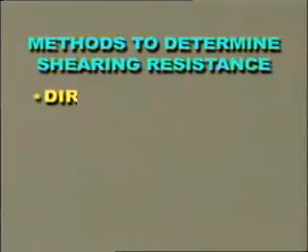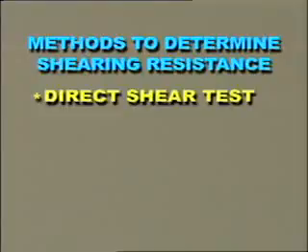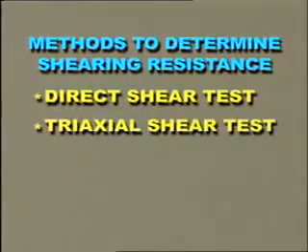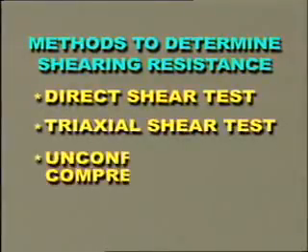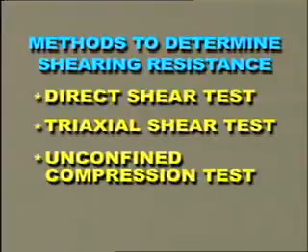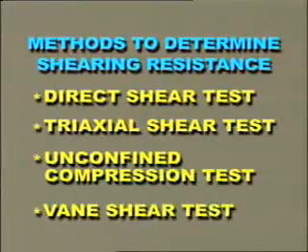The shearing resistance can be determined in the laboratory by four methods: direct shear test, triaxial shear test, unconfined compression test, and vane shear test.